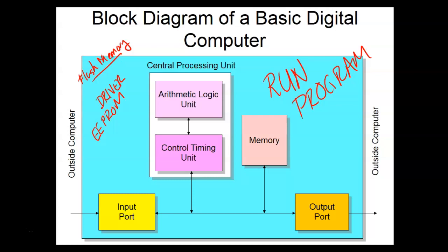So one of the things they'll use on your PLC, especially on Allen Bradley PLCs, that's what they'll say. They'll say you need to flash your ROMs because they'll come out with a new operating system. So they'll upgrade the version of RSLogix 5000, and it's no longer compatible with the ROMs in your PLC. So what you'll have to do is flash them. So this is over here on memory.